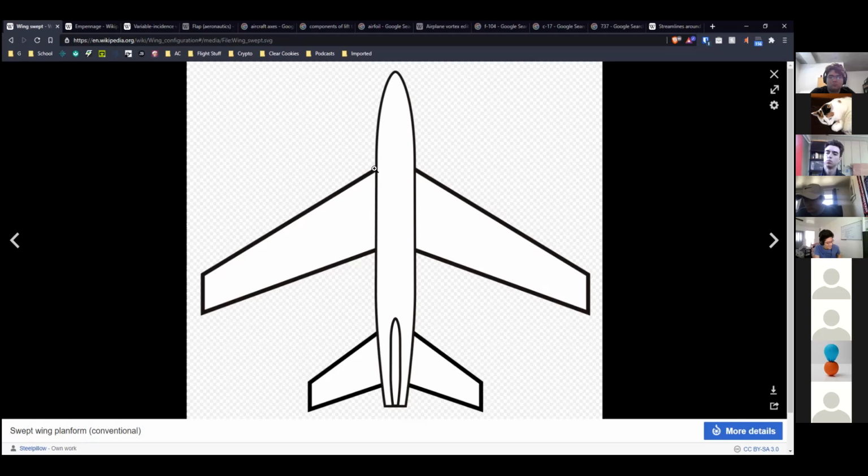So it's not a quarter of the way from here to here for this wing, but if you kind of averaged this wing out into a straight wing, it'd be a quarter of the way from that leading edge to that trailing edge. That's where you want the center of mass to fall, basically, to have a controllable aircraft. And when we start to talk about tail design and controllability, we'll go into a lot more detail about that.